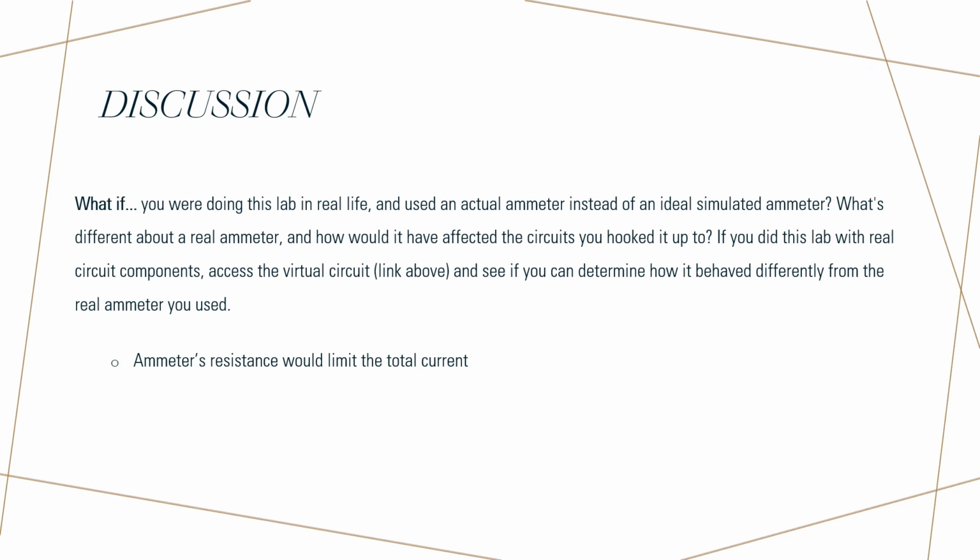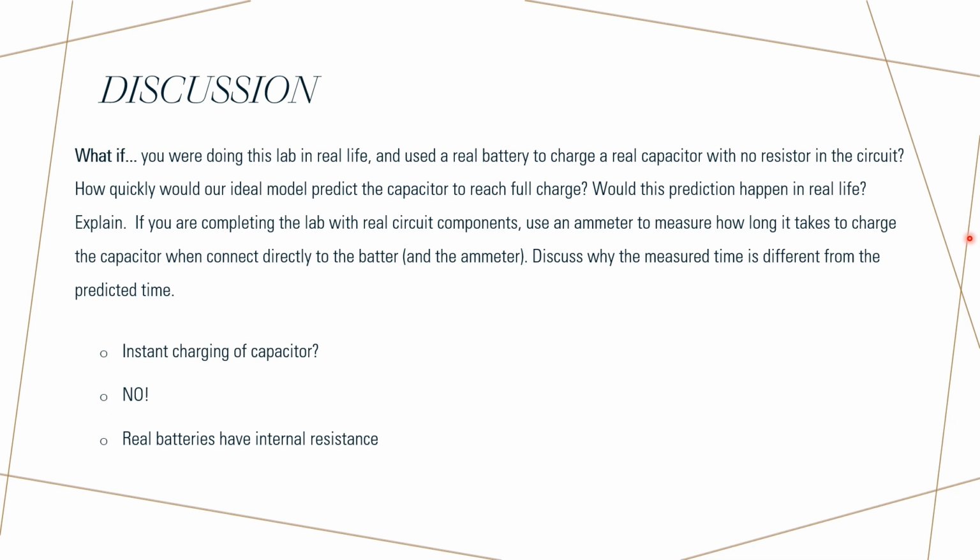Based off of our online simulation, we would assume that without a resistor in the circuit, the capacitor would charge instantaneously. However, that is not the case, as real batteries and real wires actually have internal resistance.